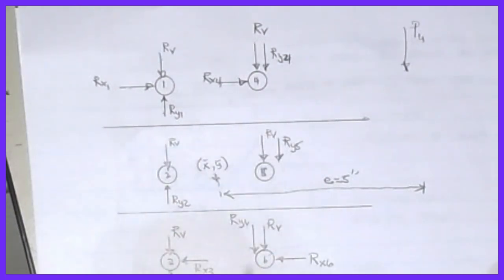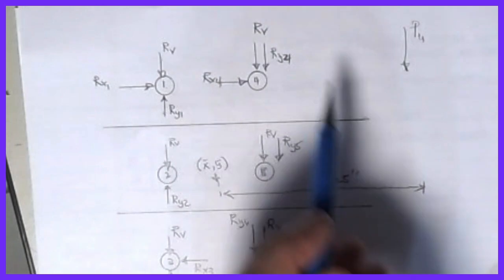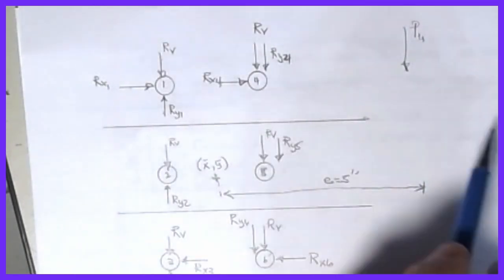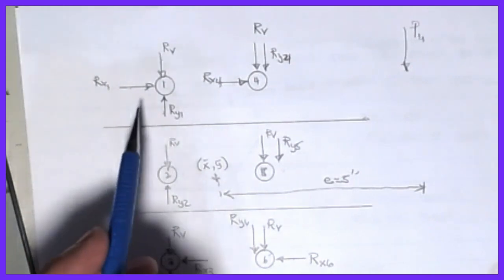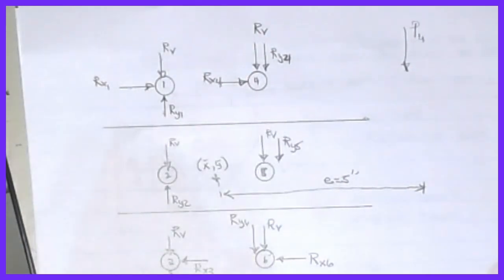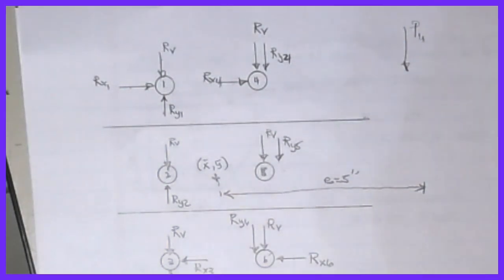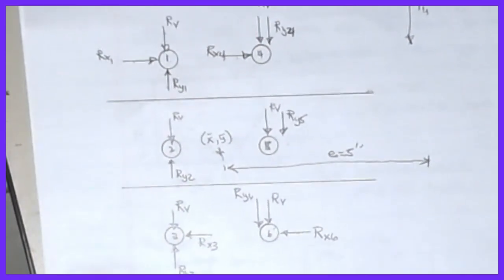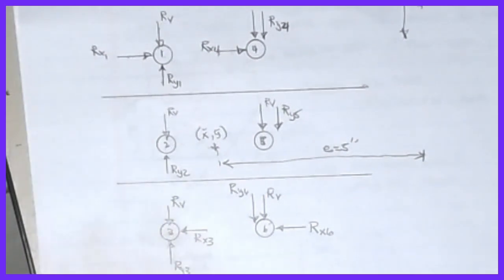If my beams and columns are sized right, I should be able to lay out a connection. And if I have a problem where I can't hold the load that I think I need, all I have to do is change the spacings of the bolts or even change the bolt size, and I can get drastic increases in capacity. So this is always kind of an after check when you're doing the connection design, and not when you're doing the upfront structural member calculations like we've been doing up to this point.